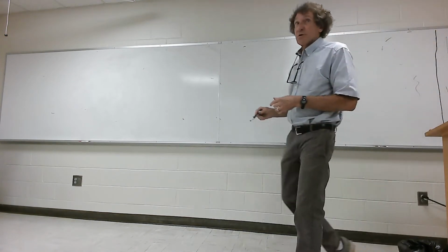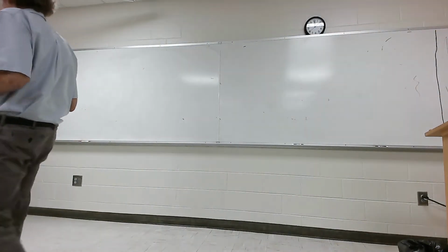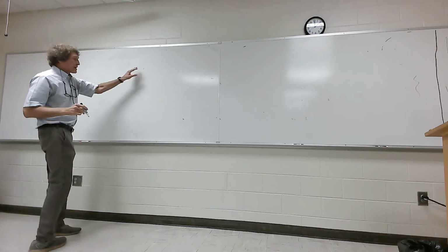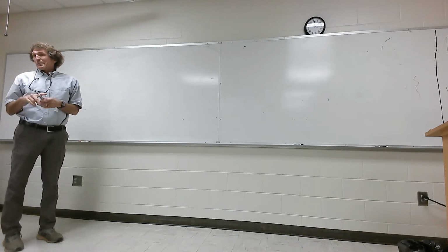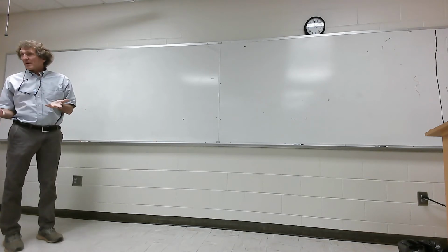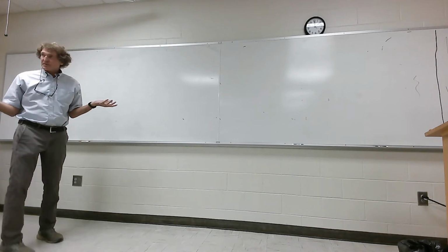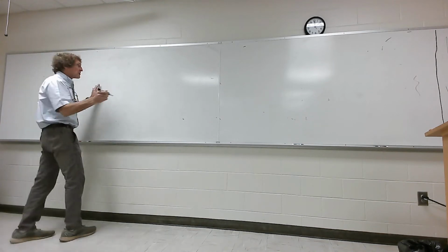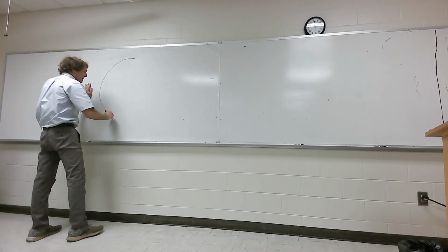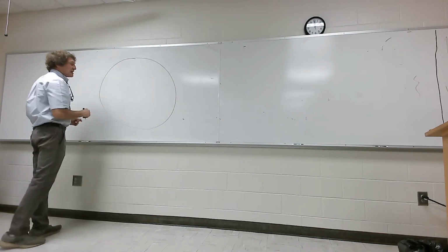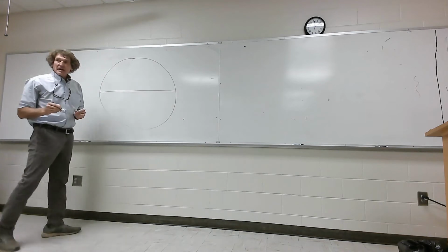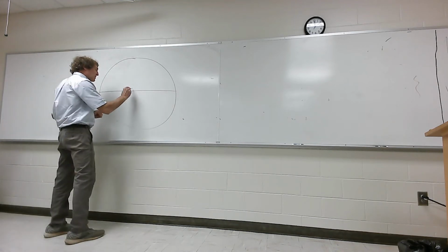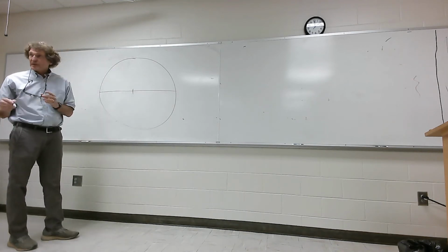All right, so you all know what a Smith chart is, right? It's basically something we use to do a lot of transmission line work, but it is not in any way, shape, or form something you have to worry about recreating mathematically. It is just the trajectories of the reflection coefficient. That's all it is. So when I do a Smith chart, I freehand them like such. That's my Smith chart, and then I put the equator in. I always do that. And then I find the center. That's the point I want to get at with any type of impedance matching.